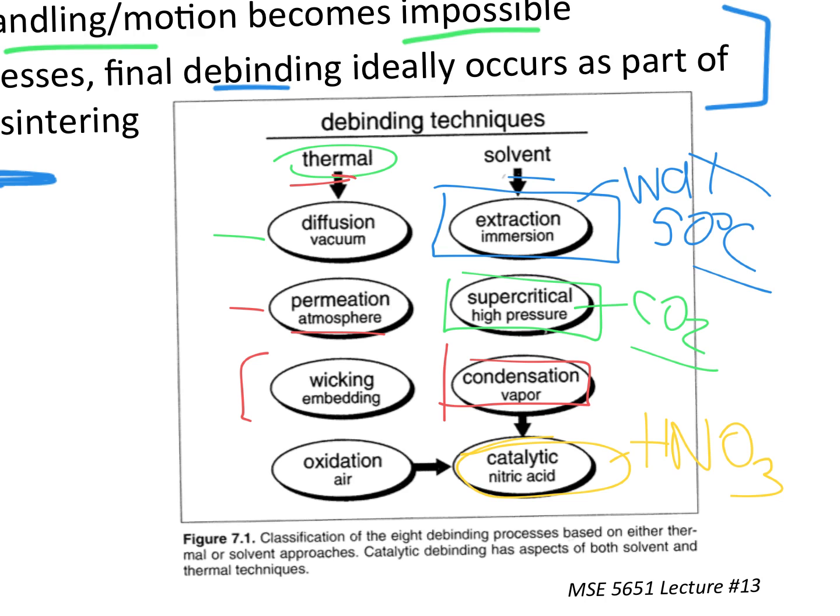So you make a polymer that's susceptible to nitric acid, and that goes in there and tears it apart at relatively low temperatures and pressures. Okay. Now you can't do this with everything because, especially for aluminum-containing alloys, nitric acid and aluminum do not get along. All right, so you have to be careful you don't dissolve or attack the metal. And then, of course, probably the least preferable technique is oxidation in air, because especially with metals, you're going to oxidize your metal. All right, so you can only use that to a limited extent, if at all.